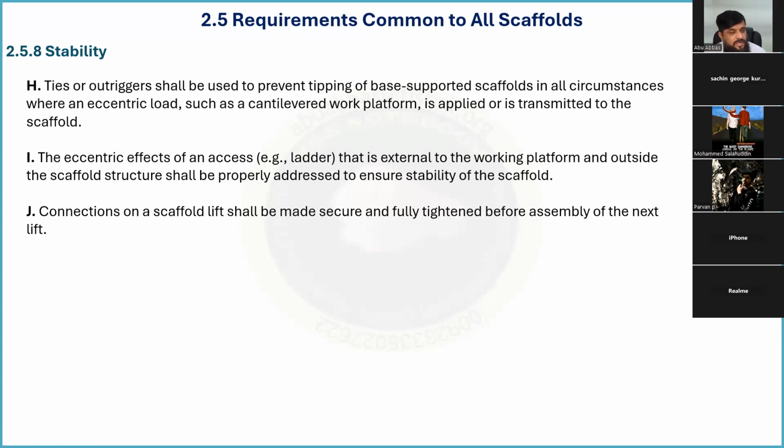Connections of the scaffold lift shall be made secure and fully tightened before assembly of the next lift. Again, whatever the connections are, there must be proper torquing, or tightening of the bolts.